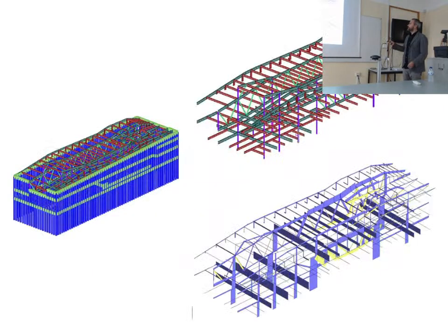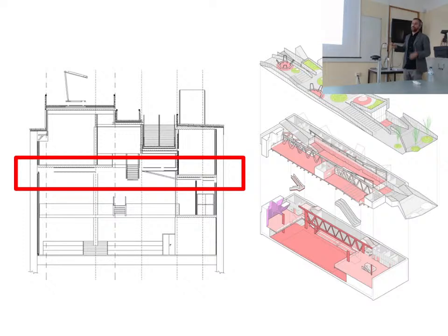So we ended up having two steel trusses, but in the main direction. We placed 4 columns around the basketball court, and we have 1 truss between the ground level and level -1, and another truss between level -1 and level -2, liberating this area for the basketball court, to have clearance for the practice. So you can see here the position of the 2 main trusses that more or less follow the volumes of the program.